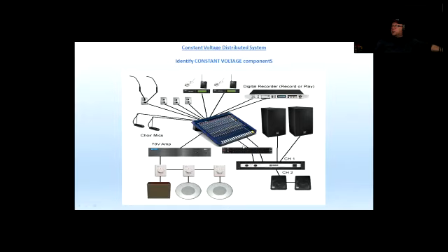So here we have the mixing board, right? We have some microphones here. We have some other microphones here. Oh, look at that. We have the other audio distributed system that is coming out of the 70-volt amp with the volume controls and the constant voltage speakers with the transformers on. And then we have some signal processing, and then we have the main speakers, and maybe we have some other speakers here for monitors, stage monitors or not. And there's a digital recorder or signal processing type of equipment here.